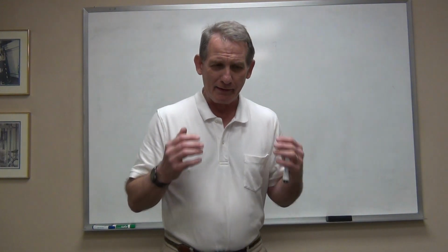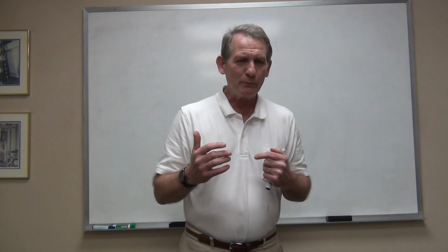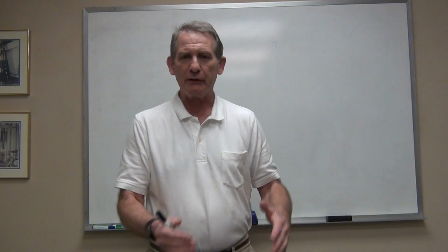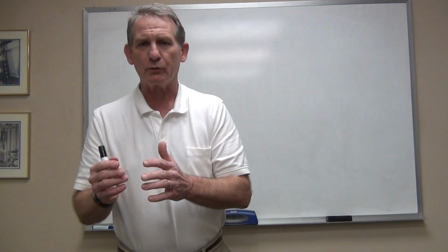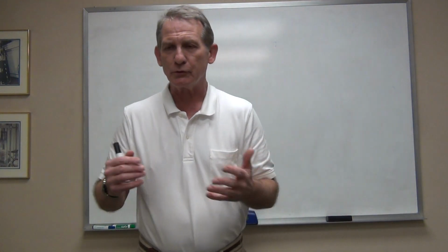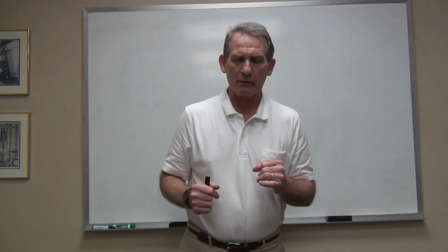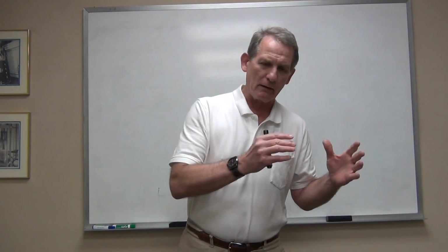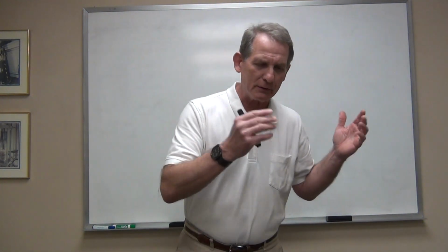And then again, if we didn't have enough complications, datums can be evaluated for their material condition. Just like the feature that we're controlling, the datum, which is a feature that we're comparing to, also has a material condition. It could be large or small or somewhere in between. So we can actually use a material condition modifier in evaluating the tolerance zone of the feature and the datum itself.